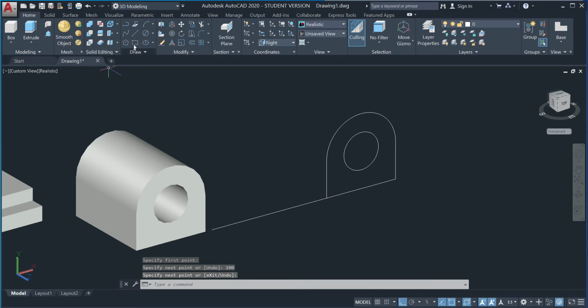Now I will select this line option again, keep the ortho mode off, track this point and draw a tangent here by tracking the tangent. Make sure that the tangent option in OSNAP is kept on. Okay, so I'm clicking it at this position, right click, enter.